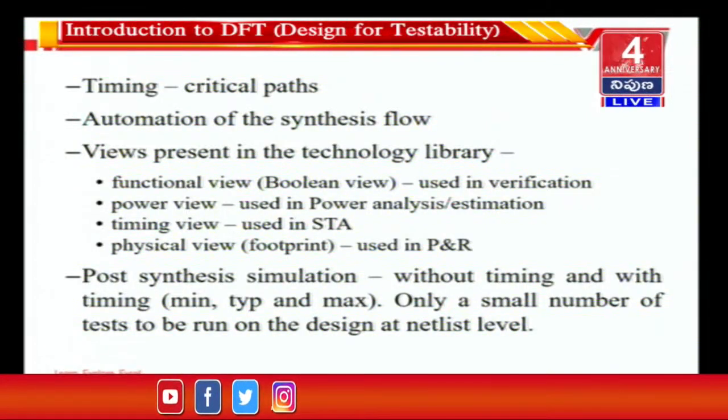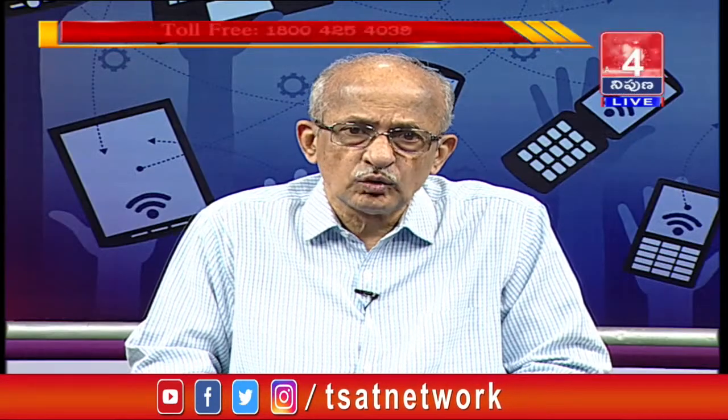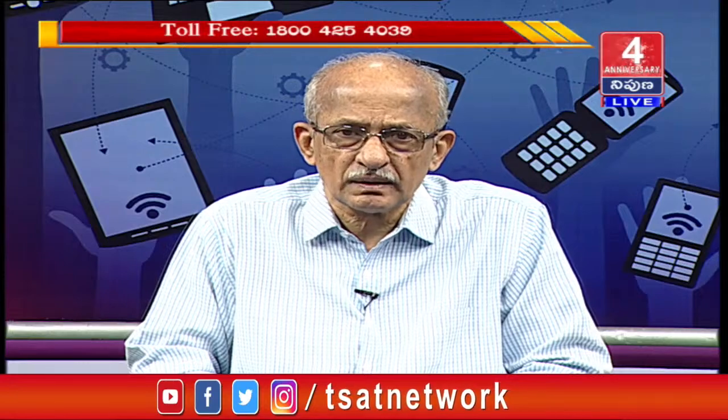From there, if we want to optimize or provide some cushion to these particular areas, then we can set the maximum delay from one point to another point as being much less than the clock period, and then run the synthesis once again, so that the synthesis tool may now try to meet these specifications given in the constraints.